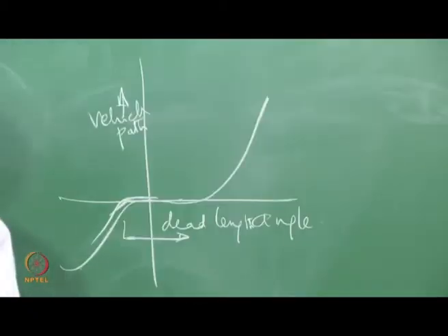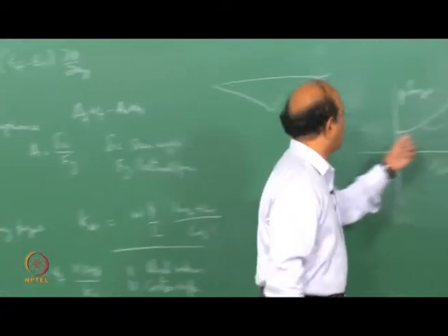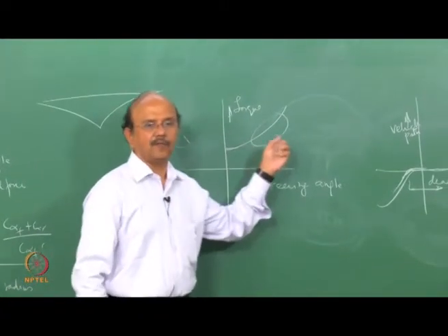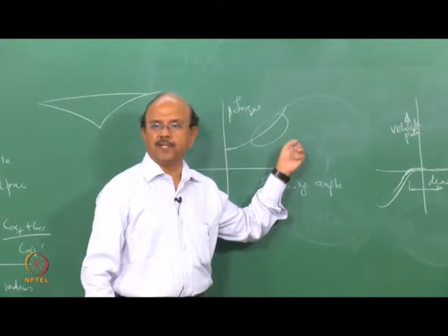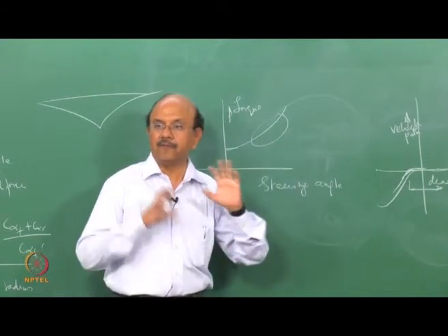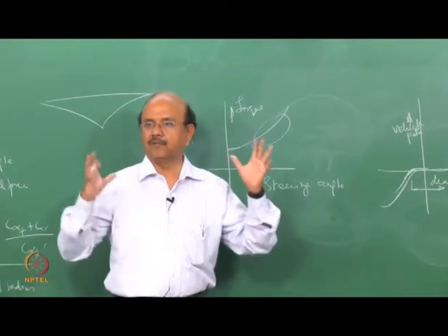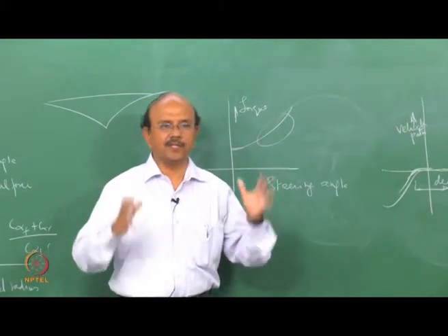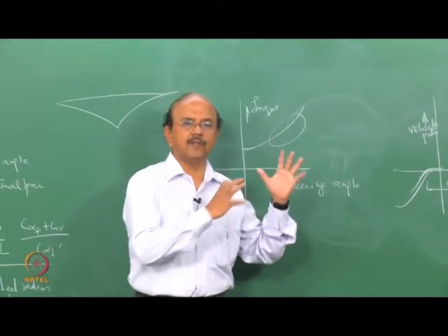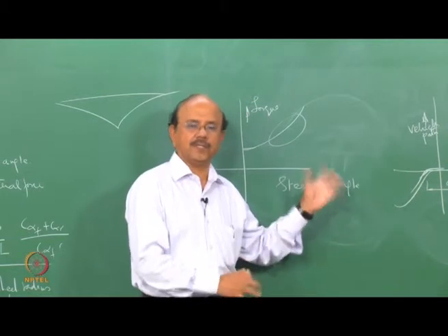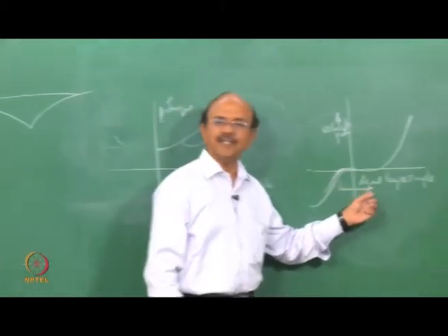Look at the subtlety. So the friction is very important. A lot of friction and a lot of compliance, my driving effort, my steering effort is going to get affected. After all, everything depends upon steering for the subjective ratings. In other words, the driver's feel all depends upon the steering. So this is called the dead length.